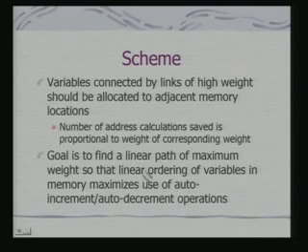I am not going into the exact algorithm to be used for solving this optimization problem, but you should understand that if I can solve this optimization problem, I shall get the optimal layout of the variables. Obviously, the assumption here is that I am using one address register for register indirect addressing. If I talk about using more than one register, or an automatic address generation unit, the problem becomes more complex.